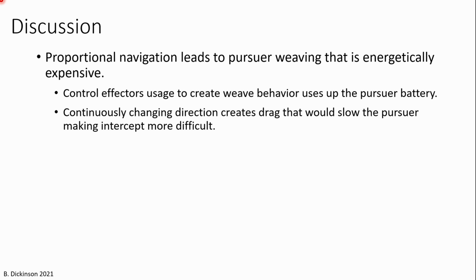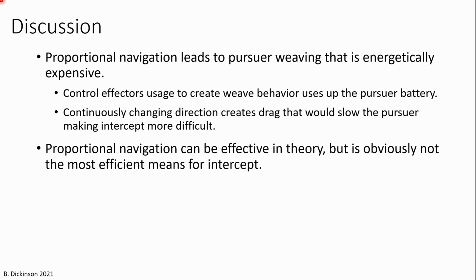But not only this, as the pursuer changes direction, the angle of attack and angle of side slip of that pursuer is also going to change. This introduces drag, which will slow the pursuer relative to the target. And as we know for Pronav, as the pursuer slows relative to the target, the intercept becomes more difficult. So in theory, yes, it's effective, but in practice, it's not the most energy efficient means.